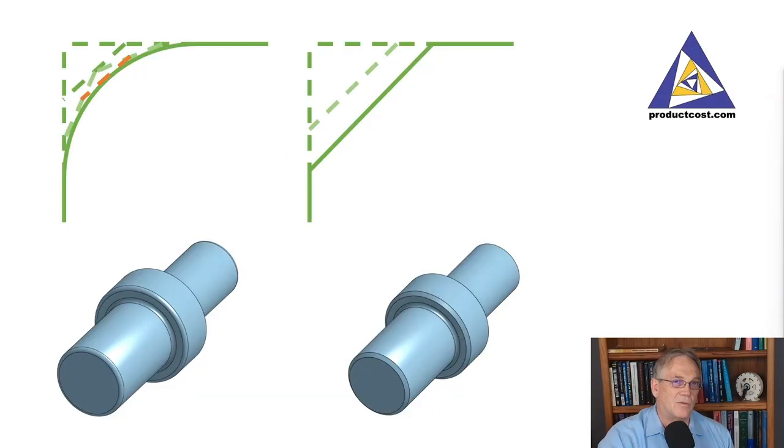In this next example of a method, this is related to machining. The method is essentially looking at using chamfers rather than fillets, if at all possible. This generally reduces the machine time, and the reason for that is if you look at how parts are machined, this being the original shape here, if it's a fillet, then with one pass you could do a rough cut, get close to the final surface, and then do a final cut here in 2 passes. You would have the chamfer profile cut.